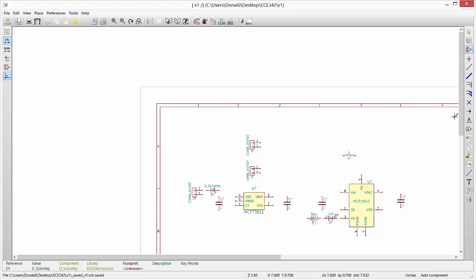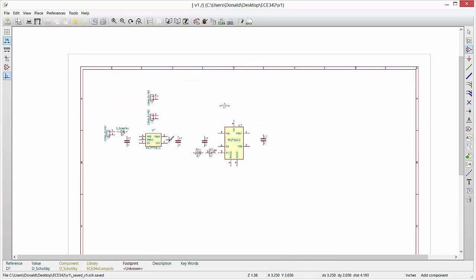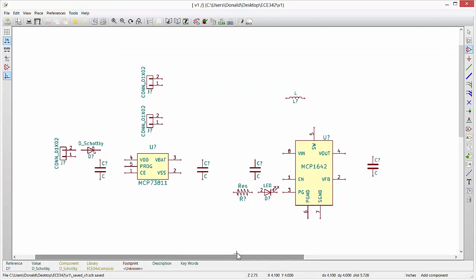Okay, so now that we've laid out a few parts, I want to touch on a couple things. You'll probably run into this if you watch any of the online tutorials about KiCad. One of the most important things when working with PCBs is to have a grid, and choose a good grid for use in the design. It's not as important within the schematic, but you can definitely make a schematic look cleaner if you start everything on one grid and you maintain the same grid.